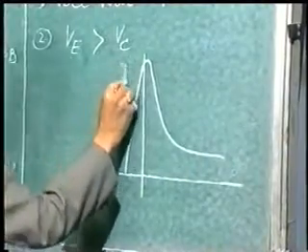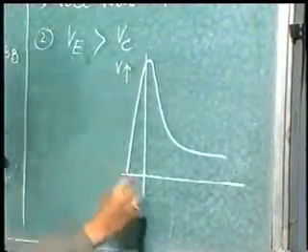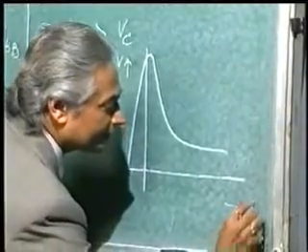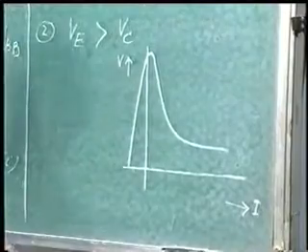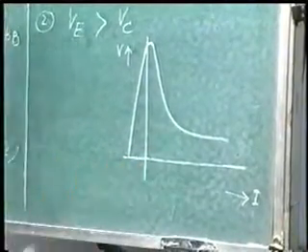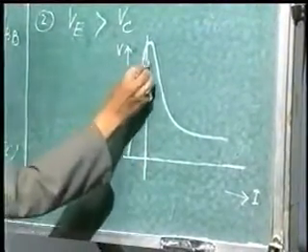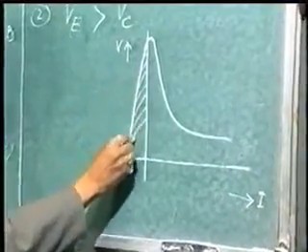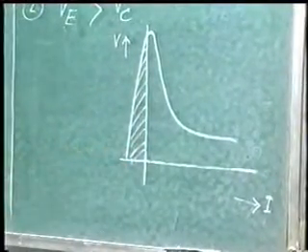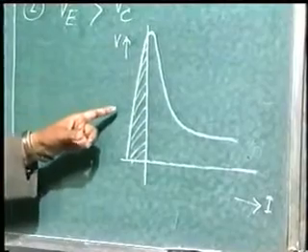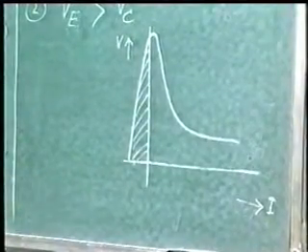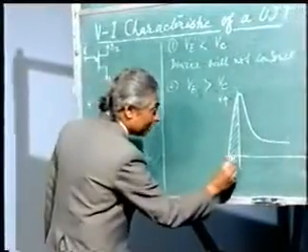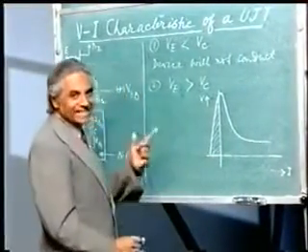Of course this is voltage, this is current, and here in the beginning there is a negative current. You see this is the negative current, and this zone where negative current is flowing, practically there is no significance, but theoretically it will happen. I told you that the current will try to flow out of the device. So this is the zone where current is trying to flow out, and it is negative current.